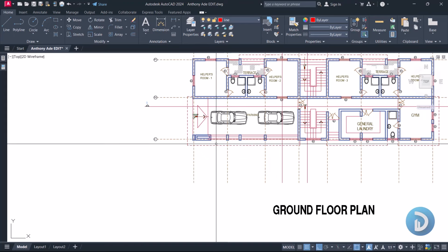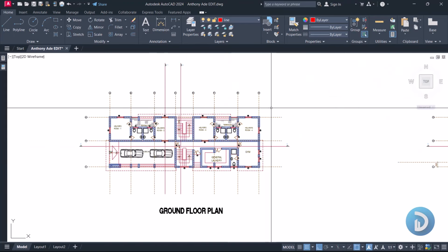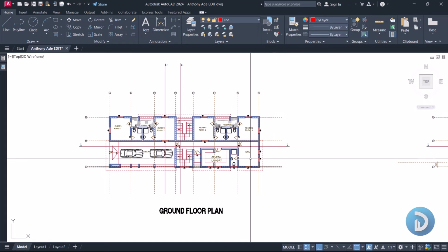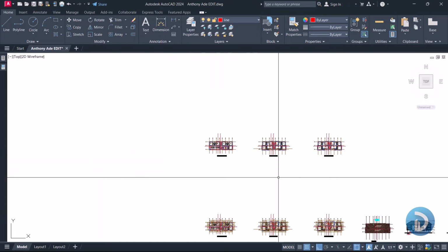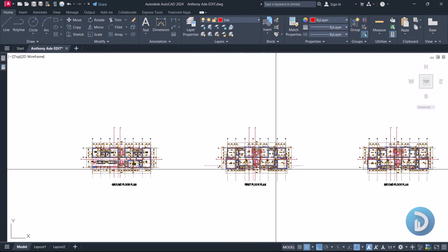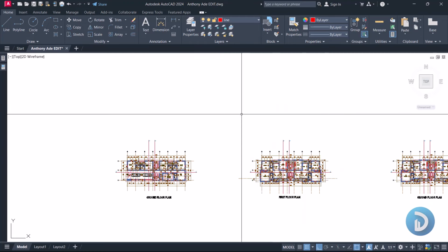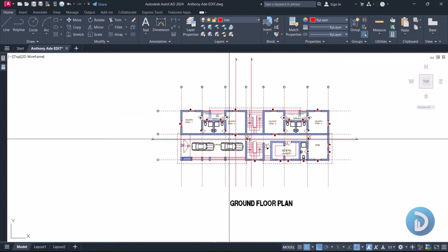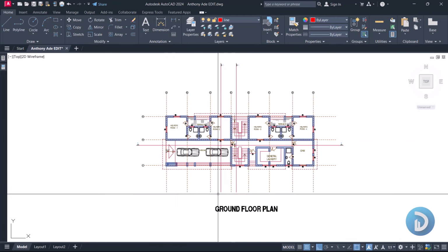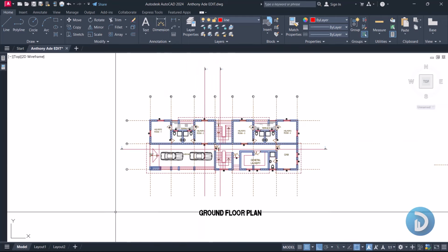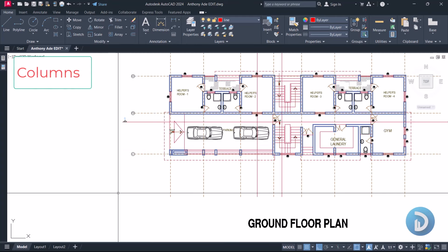As a result of this cantilever, there are chances our proposed schematic for the ground floor will not be the same structural schematics that will be applied to the other suspended floors. So we'll start off by creating our proposed column positions on this very structure. And let's keep in mind that whatever column positions we are proposing here is actually tentative and is subject to change at the analysis and the design phase.